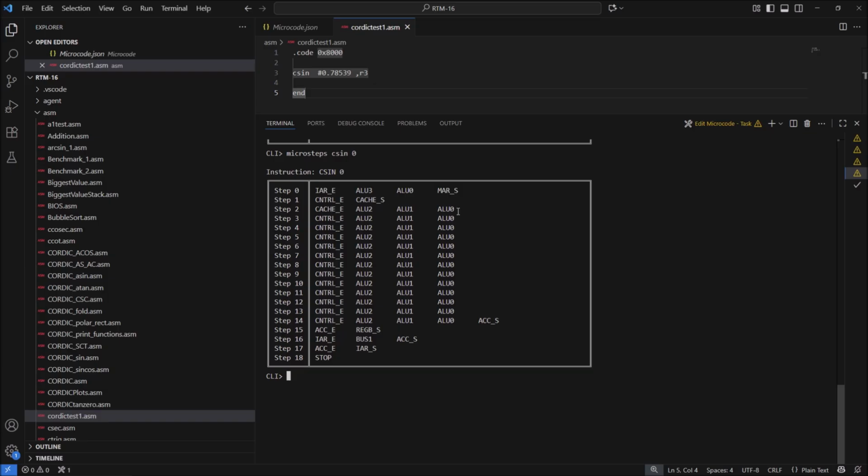And then after we've done this, the clock pulse will head on one clock pulse. So when it heads on one clock pulse, in effect we've gone through one iteration of our CORDIC unit. And then we do another clock pulse and we go through another iteration. So all of these are exactly the same and they just represent the iterations of our CORDIC unit.